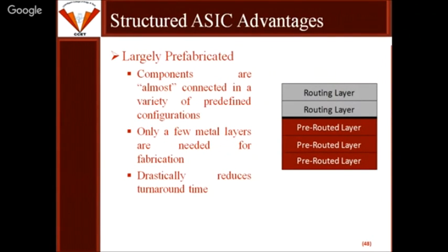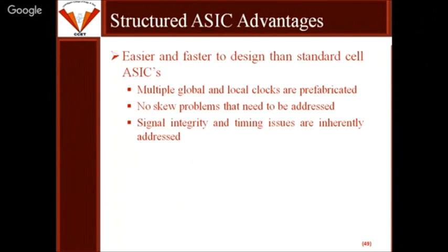The advantage of structured ASIC is that it is now largely prefabricated. So components are almost connected in a variety of predefined configurations. Having a few blocks already fabricated, and some of the blocks we have to introduce again, only a few metal layers are needed to be fabricated, and it drastically reduces the design time or turnaround time. It is easier and faster to design than standard cell ASIC.